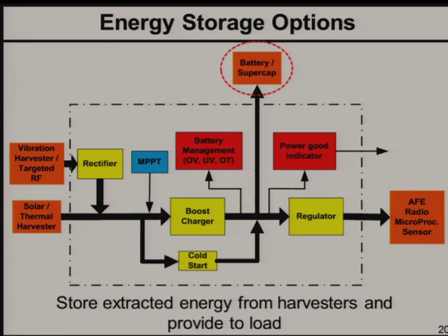So those, in brief, are the energy sources themselves. Typically, in indoor or wearable situations, we're talking about a few tens of microwatts. In an industrial or bright sunlight situation, we're talking about a few milliwatts of power per centimeter square or cube, depending on what the harvester is. And this energy is then taken out and stored in a rechargeable battery or a supercapacitor before it can be powered to the load.